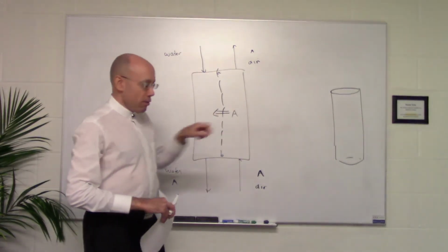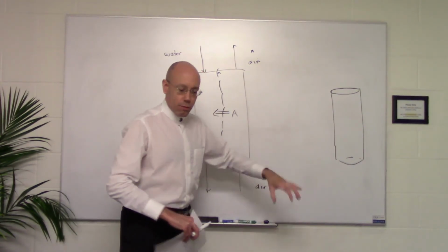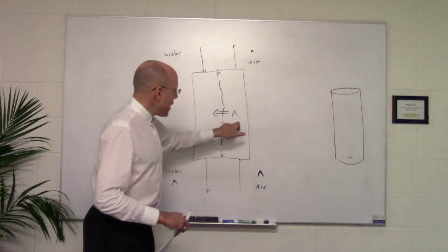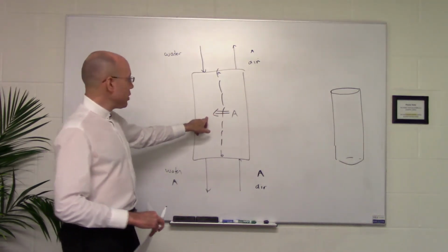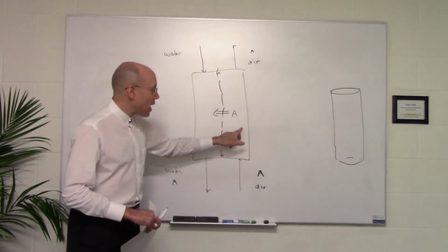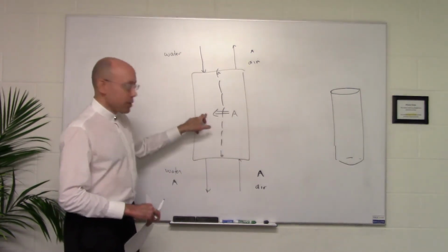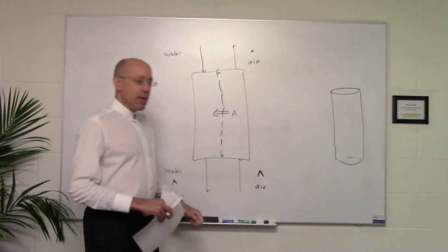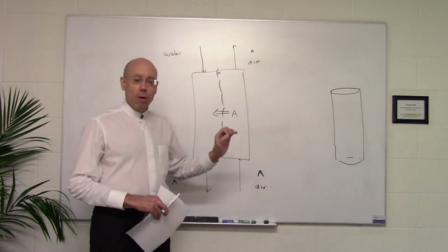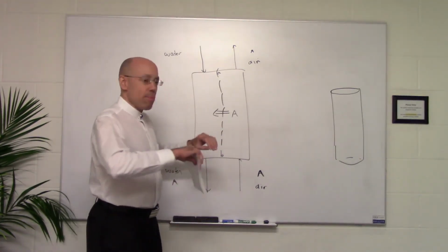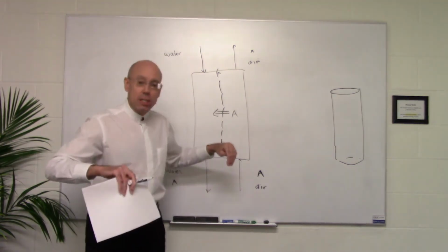So you can't individually take A molecules from a gas and pull them out, but if you can get A to go to a second phase, which is easy to separate, and let's face it, it's very easy to separate a gas from a liquid because the liquid is about 1,000 times as dense as the gas, and it just happens by gravity. If you can get any A or any component from one phase to another phase, then separating phases is very easy to do.